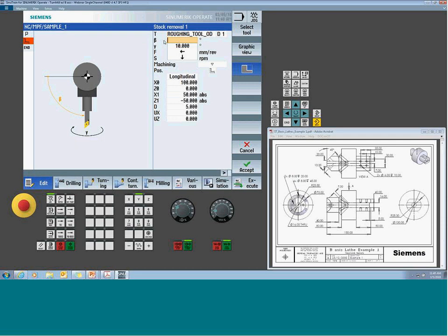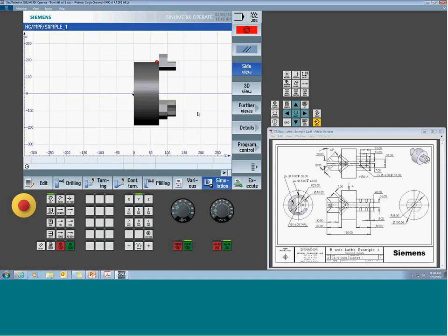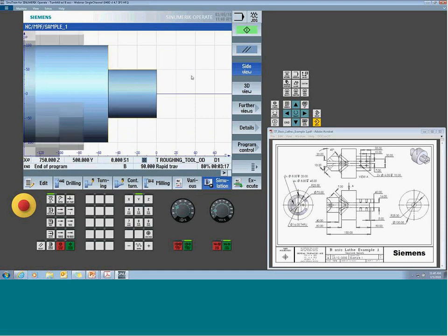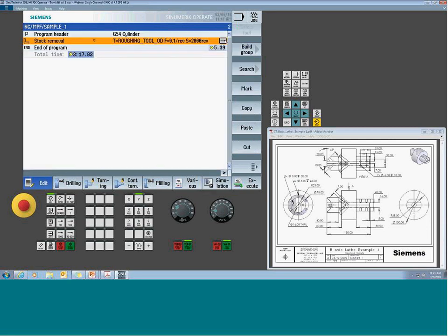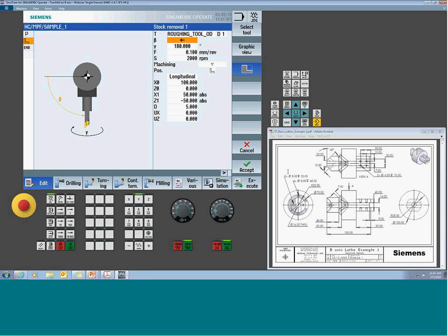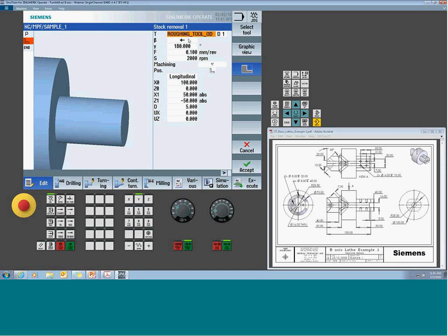Now, if I want to totally flip the tool around, right? So I go to 90 and go to 80. That's going to turn the tool upside down and move it around for me. And watch that. Because now I'm flipped over. So you can get an idea, even visually here in simulation, whether or not you see that little screw detail based on what position that spindle is in. So play with it. If you think you don't quite have your head around the orientation, fool around with it. Simulation will catch it if you've chosen a solution that's not viable or not possible.